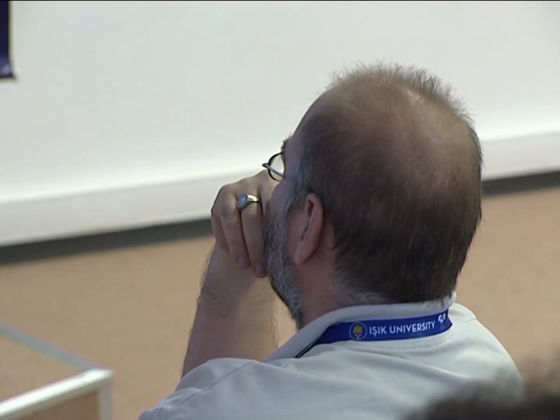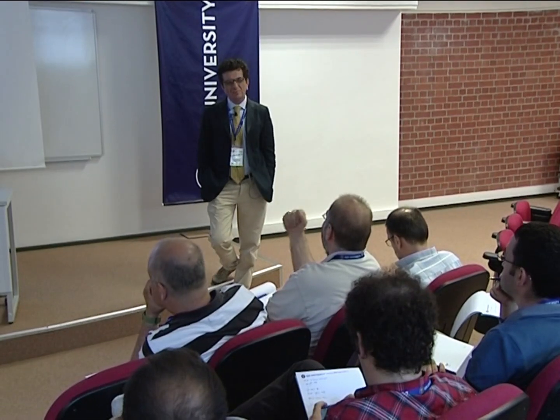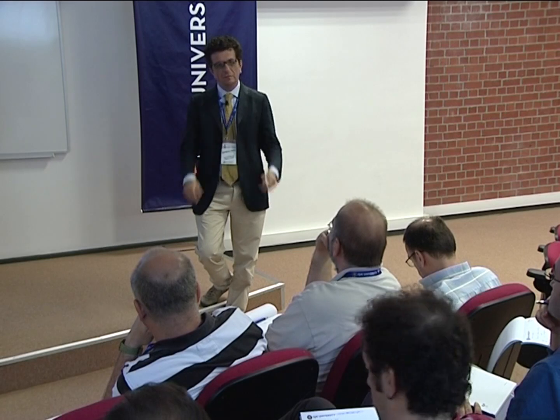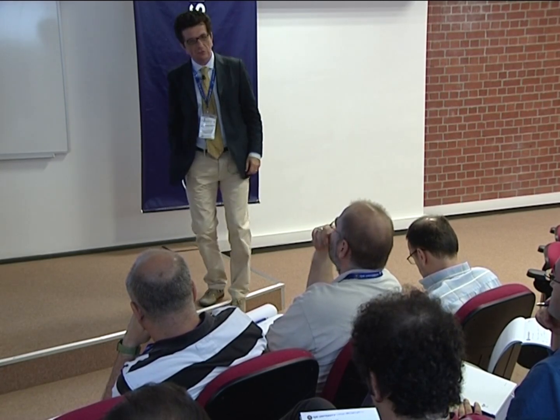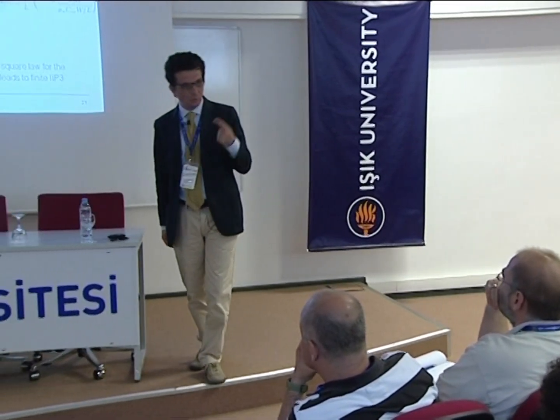Yeah, I would say also that with deep submicron, the device is naturally more linear, so you suffer a little bit less. So you go in that direction, you suffer less, and you find a compromise between the problems you say. Because large VOV trades off with large current, right? You have to reduce the W, or the aspect ratio. At the same time, the device is more linear. So the two things are going in the right direction for you. So more or less it doesn't change much. The device is more linear, but you need to be more careful.